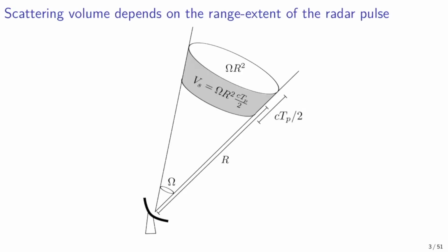In the previous lecture on measurement techniques, I told you that we obtain radar echoes from a localized volume in space. I also stated that the volume is defined by the solid opening angle of the radar antenna, as well as the range extent of the volume, which depends on the length of the radar pulse, T sub p. In this lecture, I will show how we can relate complex voltage measured by a radar receiver to the range extent of the scattering volume, which is defined by the range to the volume R and the range extent of a radar pulse, delta R. In order to do this, we will first introduce the so-called range time diagram, which can be used to visualize how the range extent of a transmitted radar signal depends on time.